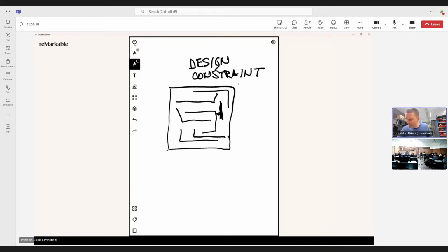Remember this constraint manager. It is used in almost all tools. And you are going to define, for example, the minimum clearance between tracks. And when you try to put your track close to the other, you will not be able to do so, or you will get a DRC error, design rule check error.